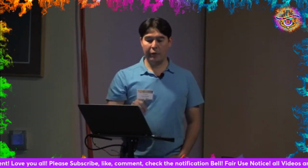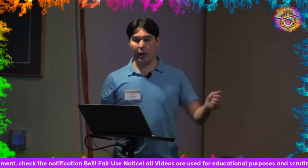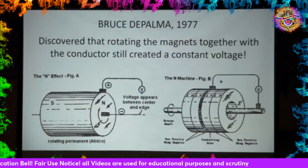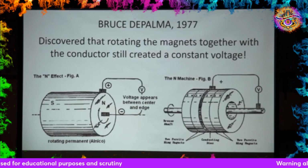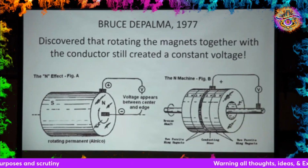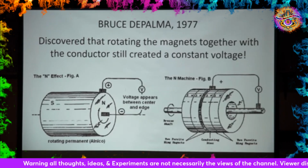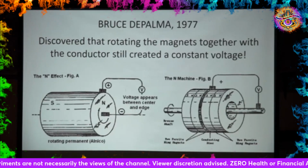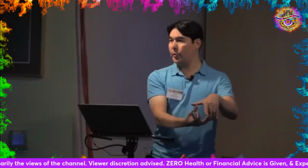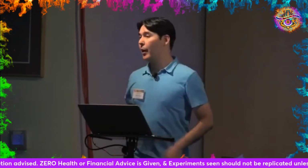But the fact is that if you take a voltmeter and put the positive on the perimeter of a spinning magnet like this, and put the negative on the shaft of the spinning magnet, you actually develop a voltage. It's not supposed to happen. What's even more interesting is that it's a very, very small voltage, almost unusable in most people's experiments. They're lucky to get millivolts spinning a magnet like this at a couple thousand RPM. But what they find is that it proportionally creates a massive amount of current.